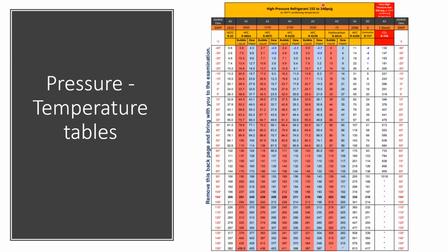If you look over here, and we won't discuss this too much, but there's these hydrocarbons. Hydrocarbons contain flammable refrigerants, okay? So they are considered low toxicity, which is the A, but they have a high flammability, which is the 3. So they will catch fire if there is a torch or something involved. All right. The next line down, this GWP number, this is also a good number.